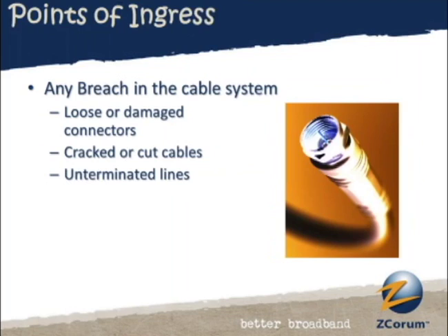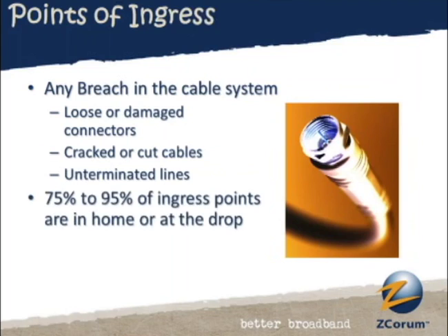Mm-hmm. So this is one of the reasons why we focus a lot on proactive network maintenance, because it helps identify impedance mismatches, which are often caused by these exact same problems. So while PNM doesn't directly address ingress noise or egress noise, in a lot of cases, the problems that it identifies are sources of that kind of noise. Right. So you can see through a PNM tool that you maybe have a squirrel chew somewhere or a loose connector, and that's going to be a source of ingress as well. Absolutely, especially in the home.